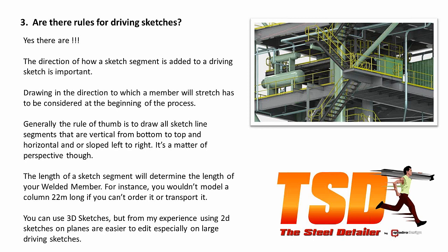You can use 3D sketches, but from my experience, I prefer 2D sketches because it's easy just to peel back the feature tree, and if I need to find something relatively quickly, it's easy to do that. You can break up your 3D sketches and get the same result. However, when you're on planes, you can swap sketches on planes fairly quickly with 2D stuff. That's just a personal preference for me.